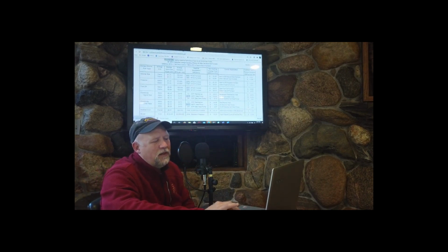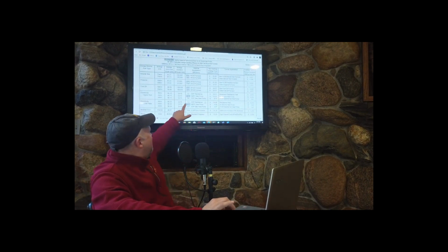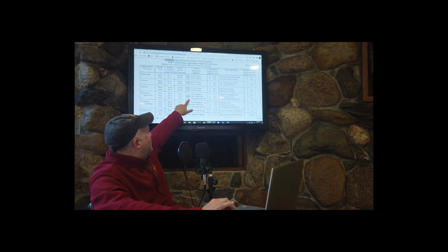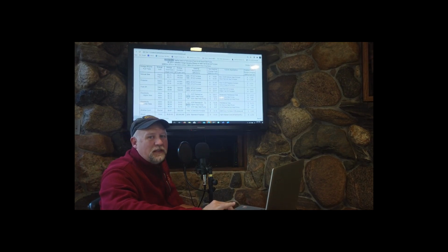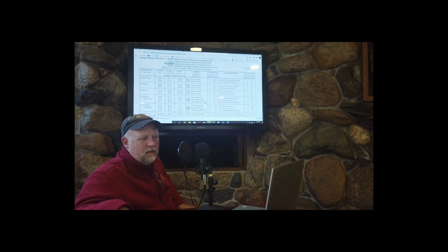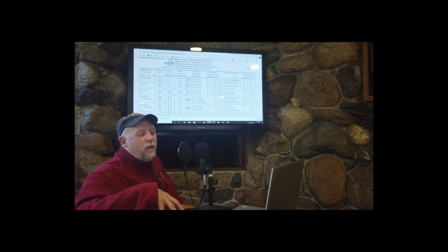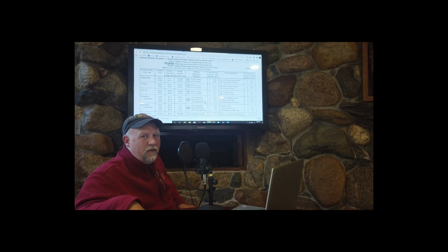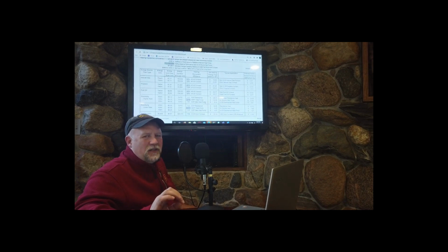All right, let's take a look at the geothermal heat pump, though. This has a coefficient of performance of 3.6. 3.6, meaning I get 3.6 kilowatts of heat transferred in the refrigeration cycle versus 1 kilowatt of electricity consumed by the heat pump itself.